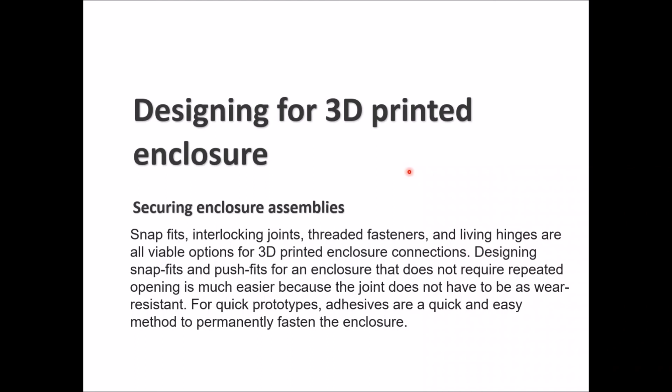If you want to design snap fits and push fits for the enclosure, this works if your enclosure is not going to be opened and closed a lot, and there's no wear or fatigue that is expected in the enclosure. Then in this case you can go with snap fit or push fit for sure, because it's easier to design and the joint does not have to have a lot of design effort in order to make it real.